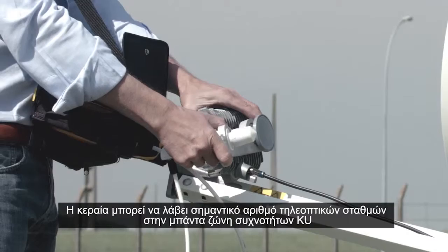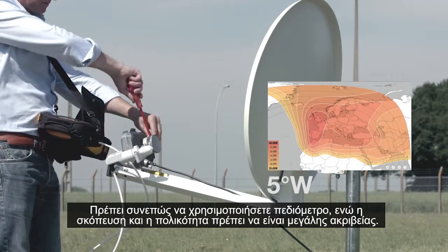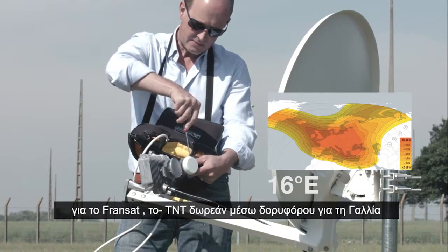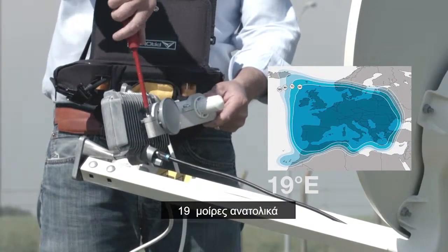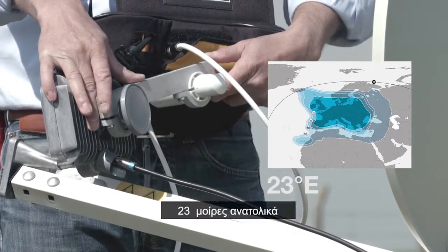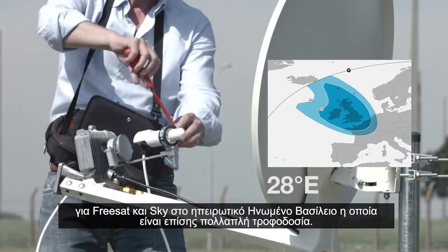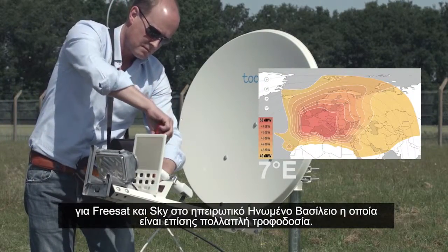The antenna will receive a large number of Ku-band television satellites. There are a number of multi-feed supports available. 5 degrees west, position for FranceSat TNT via satellite for France. 16 degrees east. 19 degrees east. 23 degrees east. 28 degrees east, position for Freesat and Sky in the UK mainland, which is also a universal multi-feed.